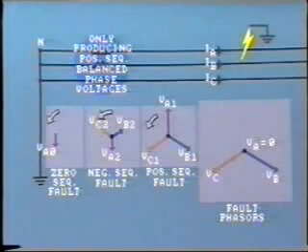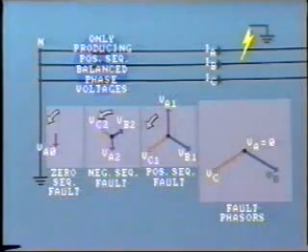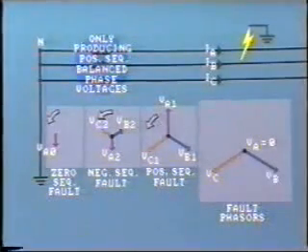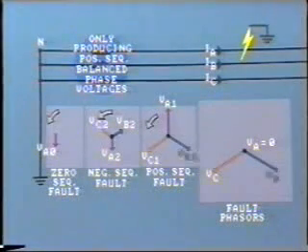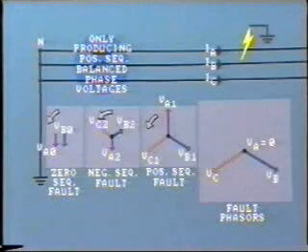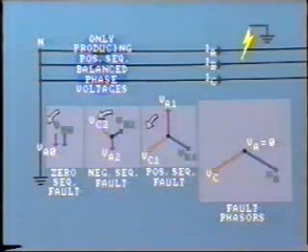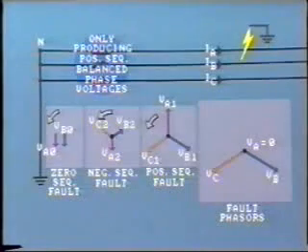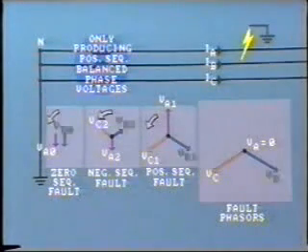Now let's look at the B phase components. We know that this phase voltage VB remains unchanged. Thus, the fault voltage VB is the sum of VB1, VB2, and the missing component VB0. Check in your workbook to verify that these phasors add to give VB.